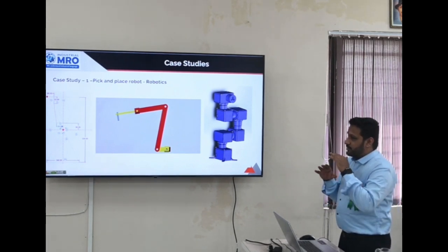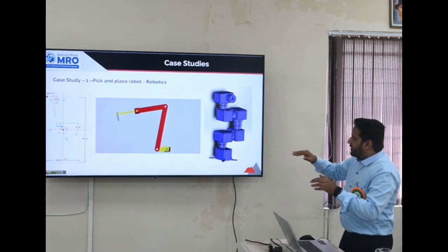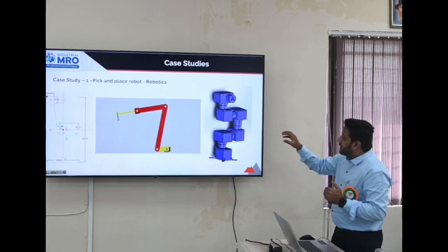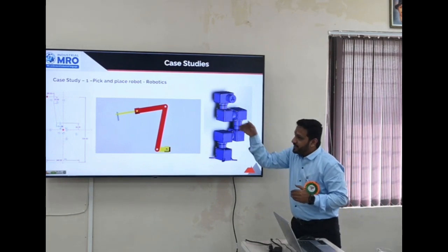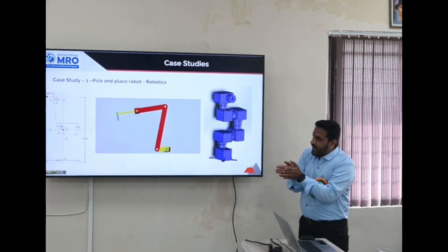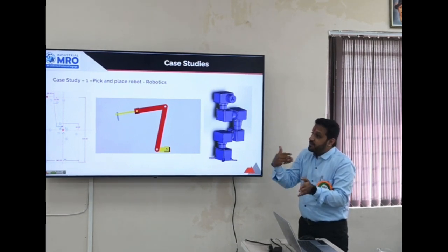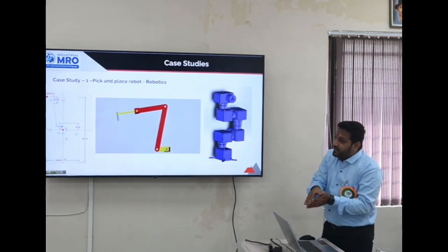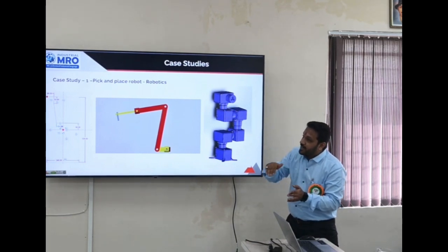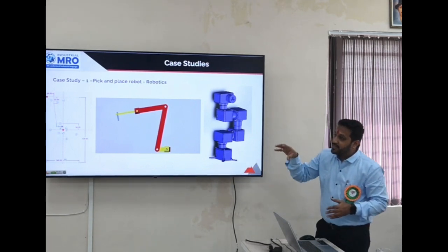So the correlation between the support and increasing the strength is that when you are adding the support, it is definitely helping you to print the part. While printing, if there is no support, what will happen in that case? The feature will deviate from what you have designed. So your part will not fit, and maybe there is a chance that it will fail as well. If you are adding the support, that means in that region the material is getting filled and supported correctly. So after manufacturing, what you will get is a good part. That is why it is adding to the strength of the part.